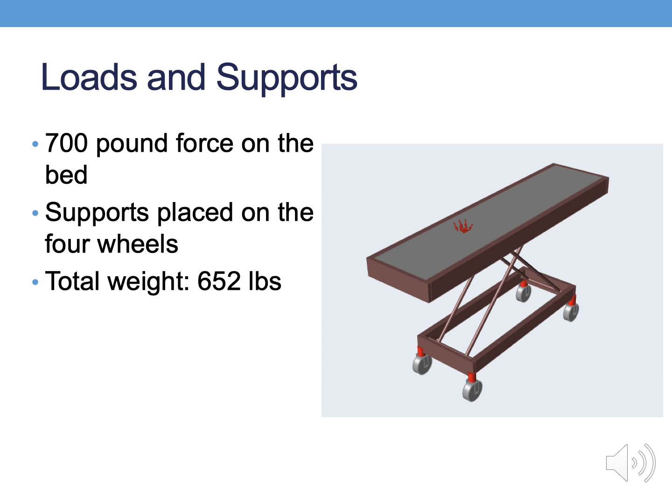In Inspire, it is possible to define the joints of the system for a more accurate optimization. Since I am concerned about the ability of the stretcher and the locking mechanisms being able to hold 700 pounds, I define the joints as locked, as this is how they would be when the stretcher is in the upright position.